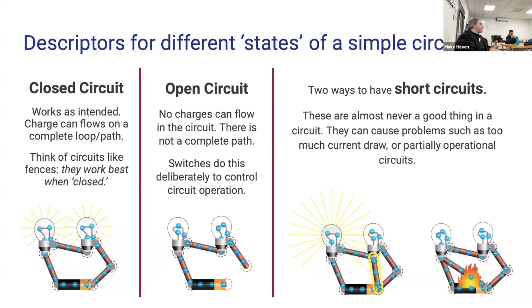Most alkaline batteries that we buy, Duracell, Energizer, it's not a big deal. They'll heat up, but they don't have that much power in them. But lithium batteries can discharge virtually all of their power very quickly, and so this type of short circuit is a big problem.